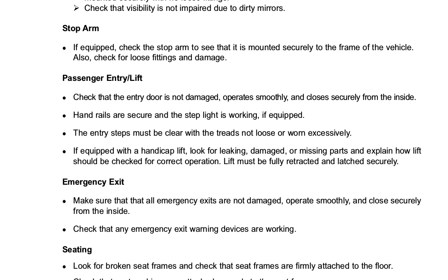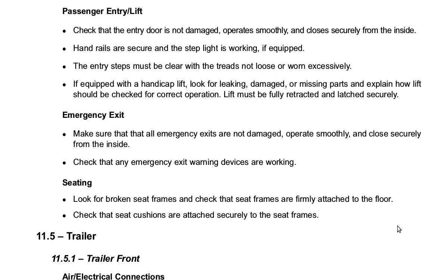If equipped with a handicap lift, look for leaking, damaged, or missing parts and explain how lift should be checked for correct operation. Lift must be fully retracted and latched securely. Emergency exit. Make sure that all emergency exits are not damaged, operate smoothly, and close securely from the inside. Check that any emergency exit warning devices are working.